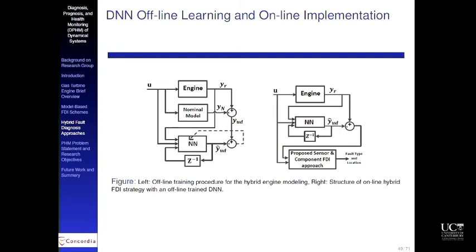What's the big deal? This diagnostic system that I designed was based on what model? This model. So to make sure that my diagnostic system will not have any false alarms and false classifications, I want to make sure that this diagnostic system is operating with the data that has removed the unmodeled dynamics. So it is operating as if I'm just applying it to the nominal system.